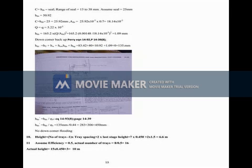The formula to find out HL is also given here. HL you are getting is 18.66. So phi E you know, so you will get HF, the total height, as 41.4. Whatever you assumed, 40 mm, is more or less correct. So liquid hold up is also okay.